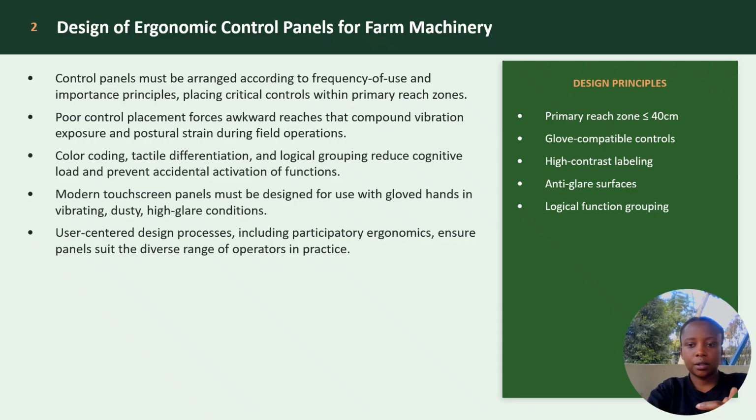The second one is that poor control placement forces awkward reaches that compound vibration exposure and posture strain during field operations. The third one is that color coding, tactile differentiation, and logical grouping reduce cognitive load and prevent accidental activation of functions.